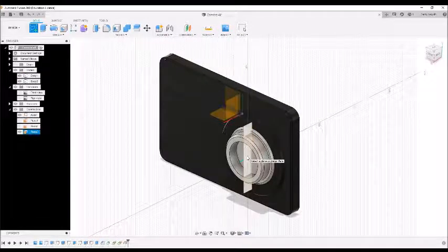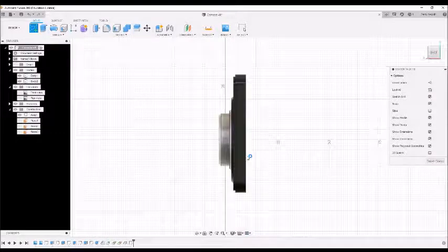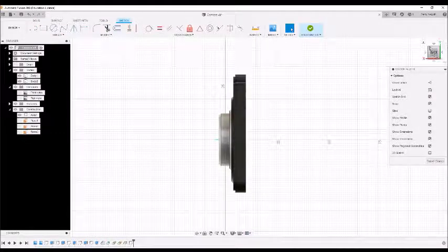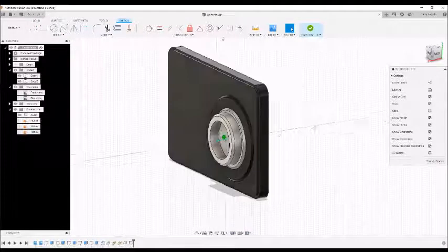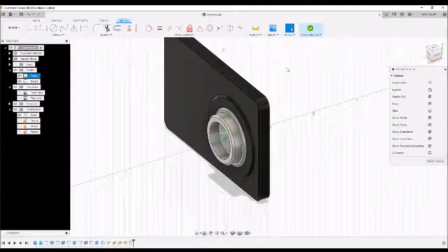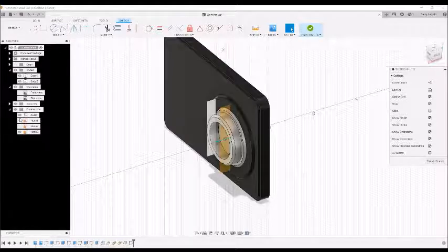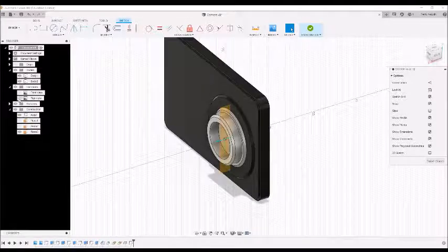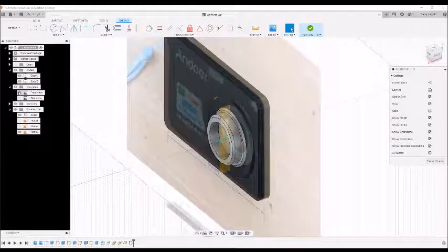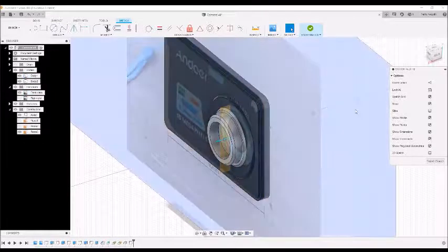Now I'm ready to start setting up my revolve profile sketch. So I'm going to create a sketch on the work plane, the mid plane in the cylinder, just by selecting the work plane, and I'm just going to very quickly draw onto that side plane there.